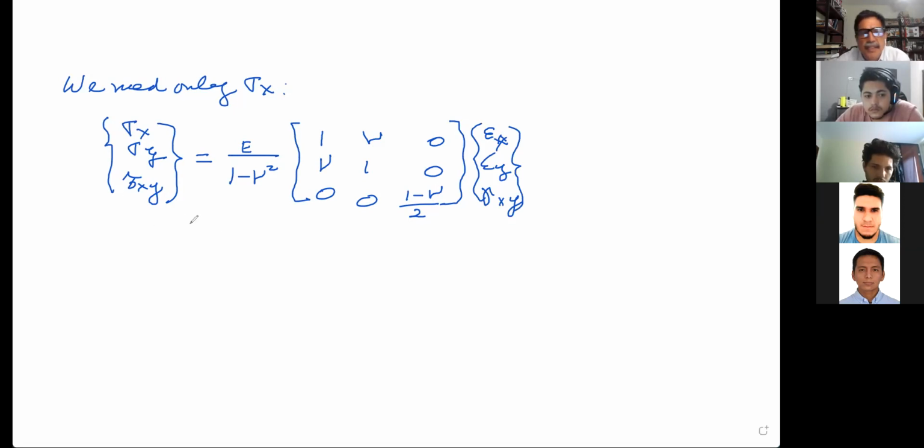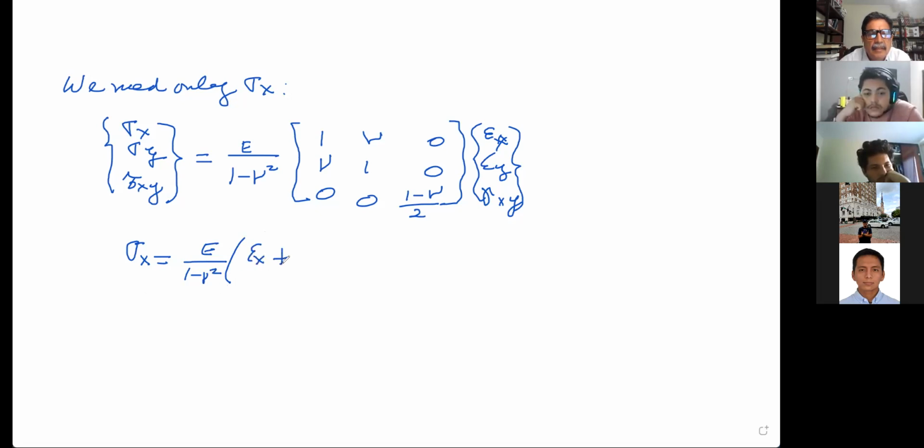So tell me, Mr. Iñiguez, how do you calculate sigma x? Sigma x is equal to what? Come on, you can multiply this. Mr. Arias, can you multiply this? The Young's modulus divided by 1 minus the Poisson ratio, multiplied by epsilon x, plus epsilon y multiplied by the Poisson ratio.